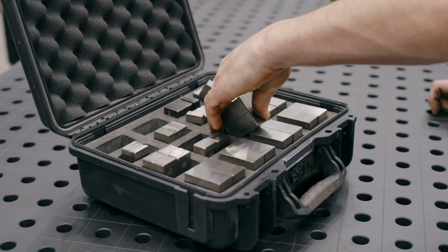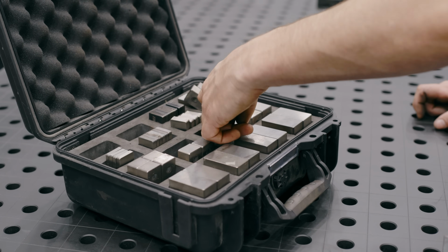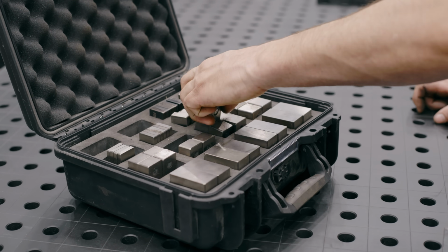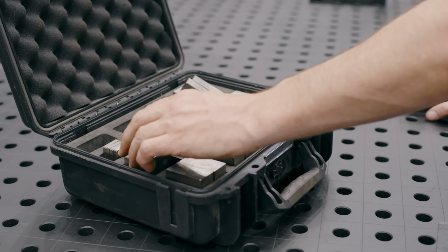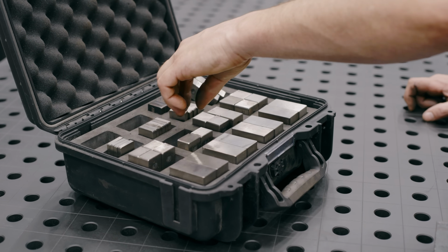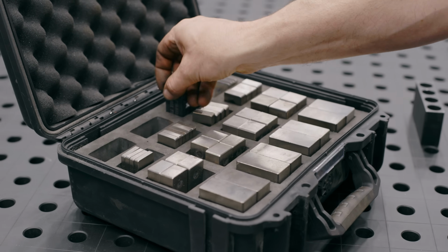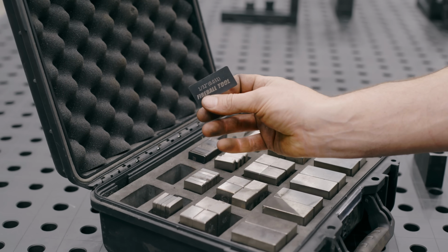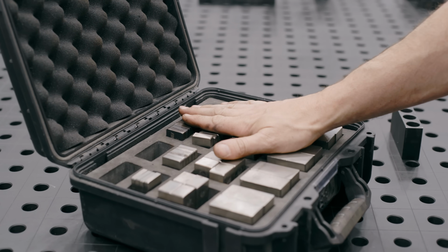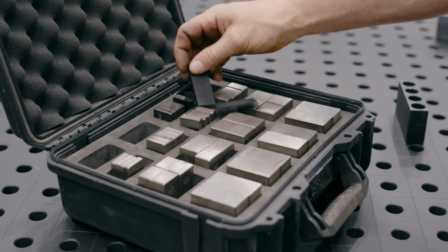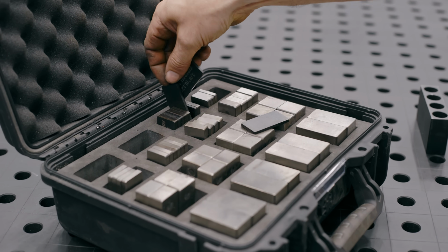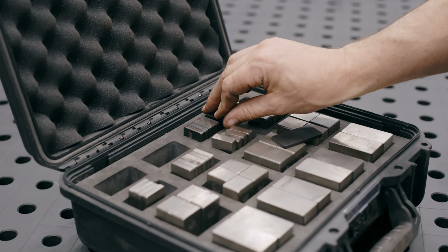All right, setup number 2 requires these shims. This is a great assortment of spacer blocks. These are all machined parts. We have 2x2 blocks, 1x2x1, just about any configuration you'd want, all the way down to 1/32 of an inch. Some of these are magnetic, some of them aren't, depending on the thickness, okay? So for this demonstration, it looked something like this.